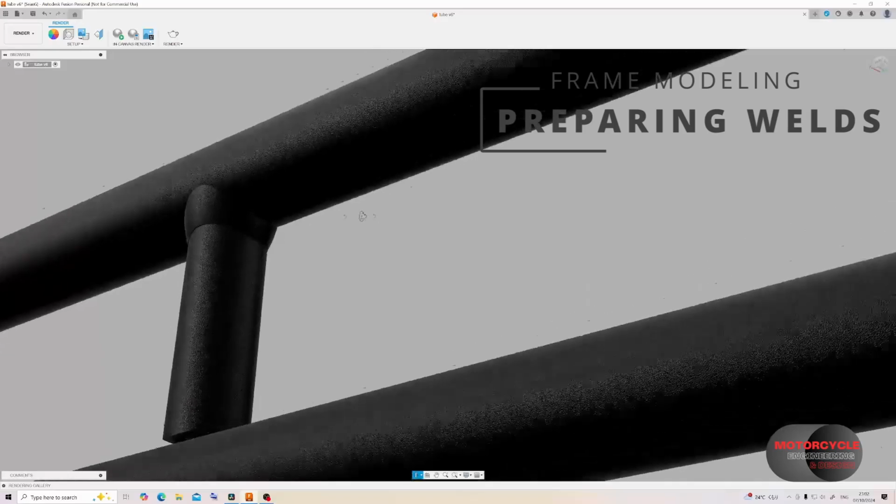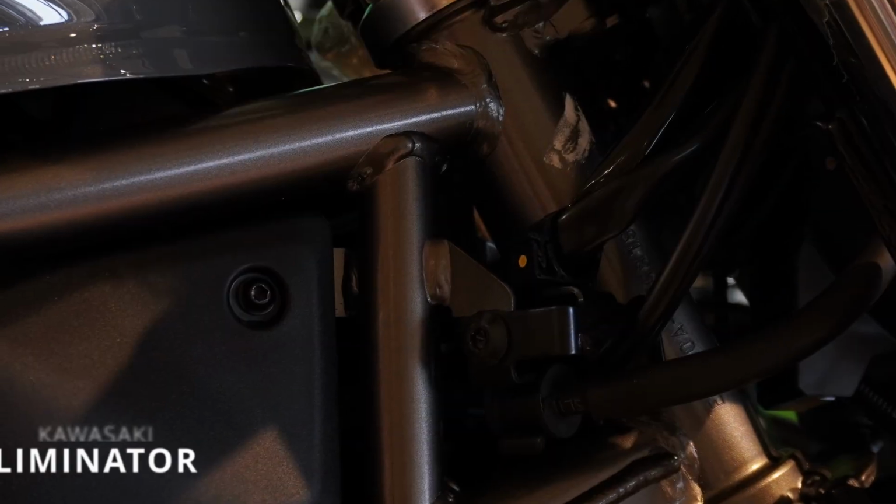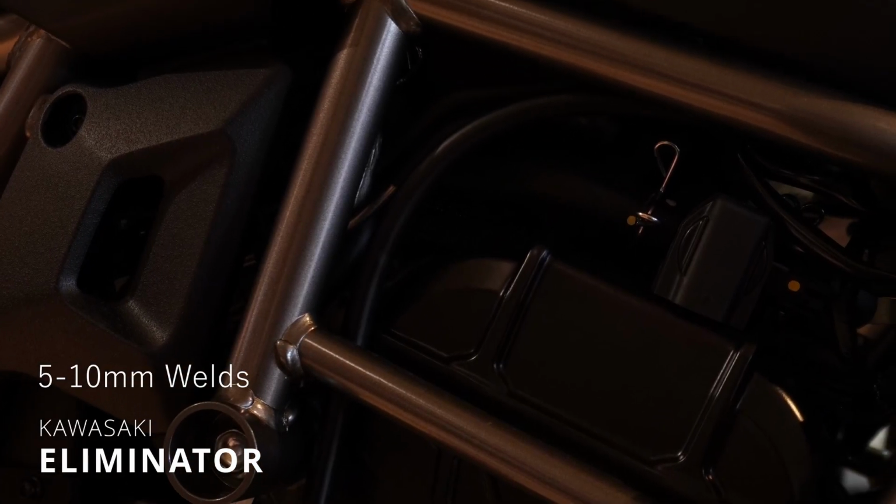So the first thing I'd like to draw your attention to is the shape of the weld. See, they're actually more convex than concave. And whilst there's variation throughout the weld, we should always consider the worst case for packaging.